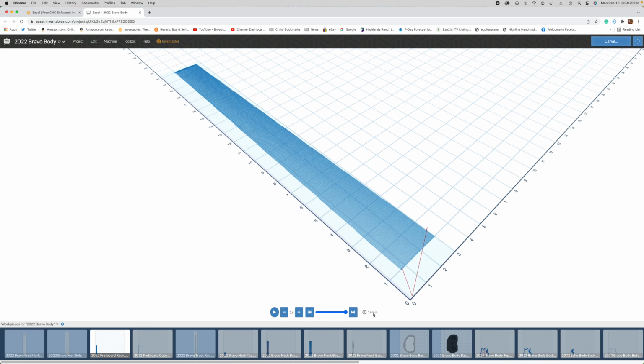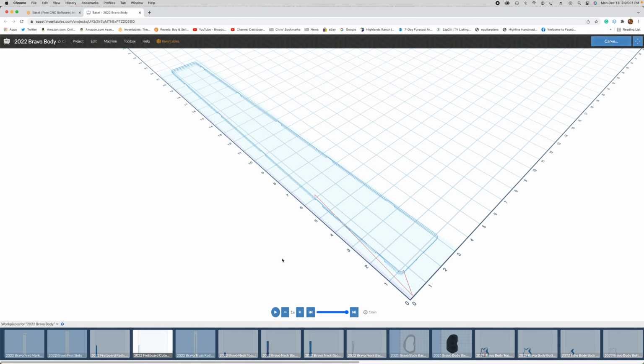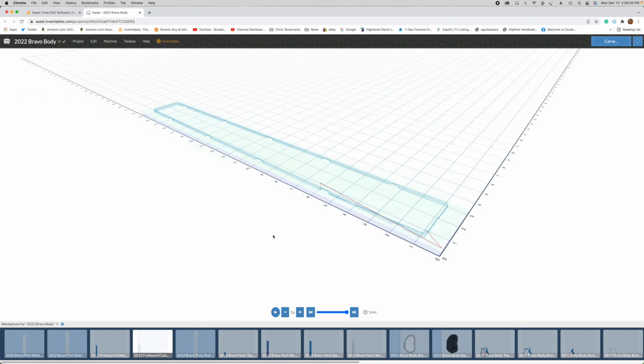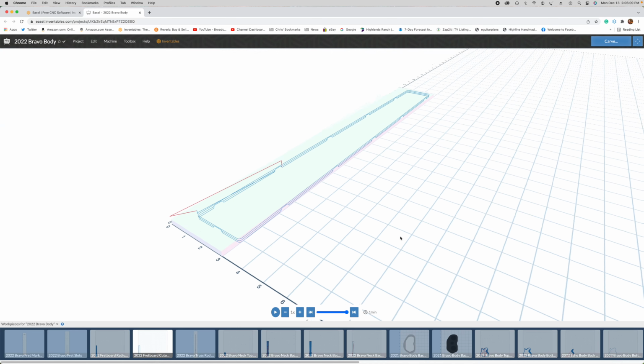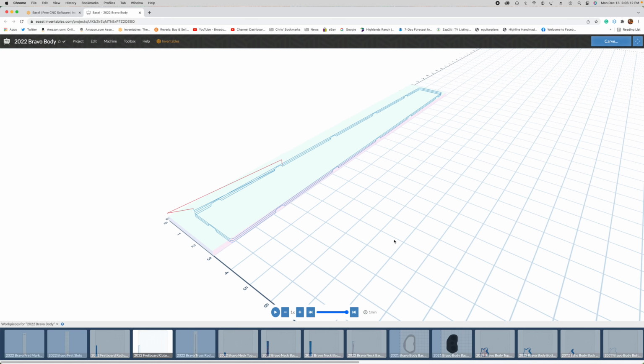And you can view a simulation of the movement of that parallel finish with that 1/2 inch round nose bit. But then once that's done, the spindle will return to the work 0 position, and then I can swap out the bit for my 1/4 inch diameter 2-flute spiral upcut bit, and I can then carve my cutout. So this takes about a minute. And that's really all there is for setting up and carving the fretboard.